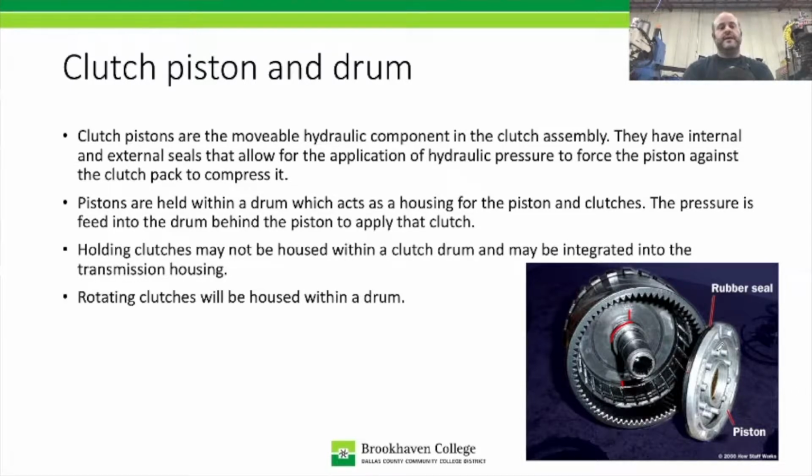So pistons are held within the drum, which acts as a housing for the pistons and clutches, and the pressure is fed into the bottom, behind the piston, and that causes the clutch to apply. Now the holding clutches, so that would be what I just described, would be, usually on a driving clutch, a clutch that's actually going to be spinning inside a drum.